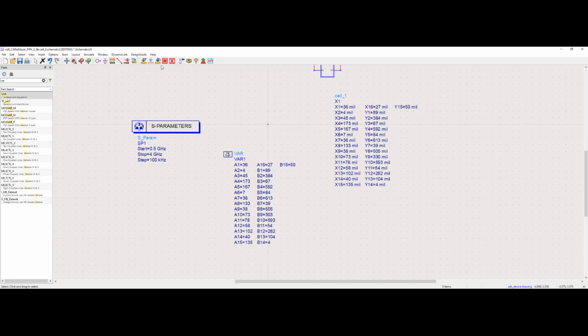After that, insert the newly created parameters into the EM model. After modifying one parameter, press Enter to arrive at the next. This parameter redefinition is done because the optimization can only be done via a var. I will fast forward this process as well.